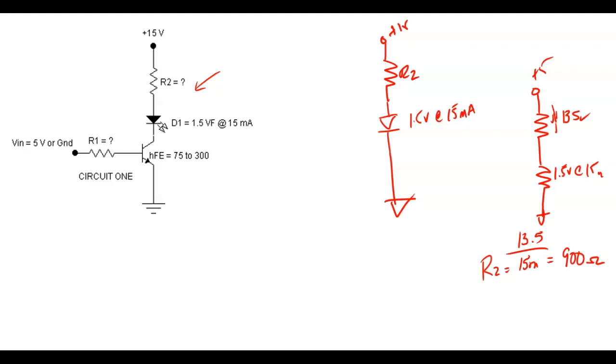So did this calculate to be 900 ohms exactly? That was the part that I got right on that one. Definitely. I got that part right. Okay, so here, what did we choose? You're going to choose 910. And what's the power? I squared R, you can use V times I, right? 910. Of course, we would probably have to recalculate the current to be exactly right.